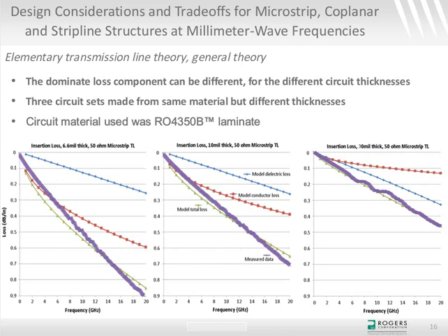To start off with the chart in the middle that's got the legend, that's using 10 mil thick microstrip transmission line, 50 ohms, and the thick purple curve is the measured data that I got. That's going out to about 20 gigahertz, and the y-axis is loss in dB per inch. The other curves are a model from our MWI 2017 software that's free for download from our tech support hub. The green curve is the total loss, which should match the measured loss. And for what we're doing today, that's pretty good. That's pretty close.